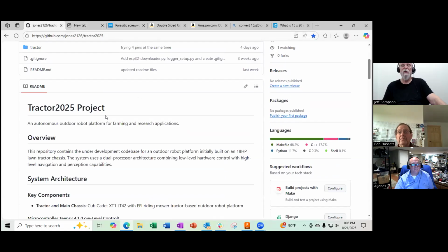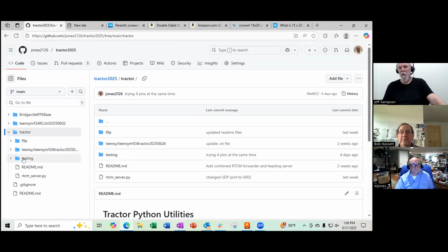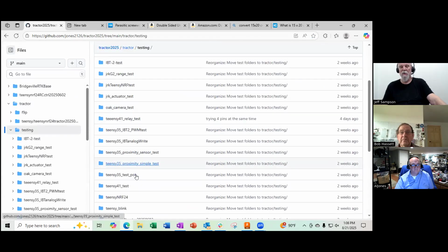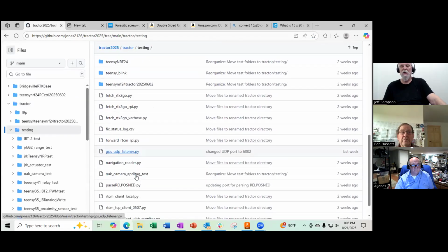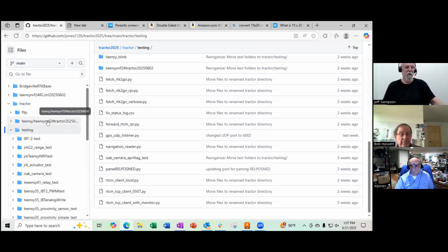Okay. Because one time I had that same problem and I found somebody's NTRIP client that runs as a ROS node. So I could start that up and it would get the correction data and publish it as a ROS topic. Then I took the u-blox driver that was talking to the USB board and hacked it, putting in about 6 extra lines of code that subscribe to this correction data as a topic and multiplex it going out to your GPS board. That's how I solved it then, and later I moved on to doing it other ways, so I'm not doing that anymore.